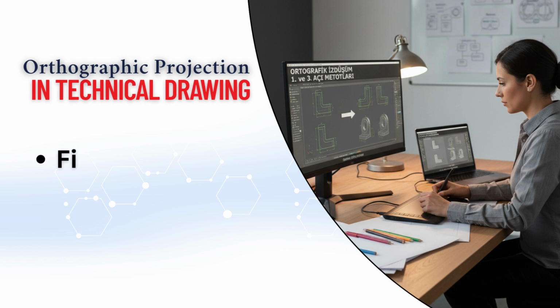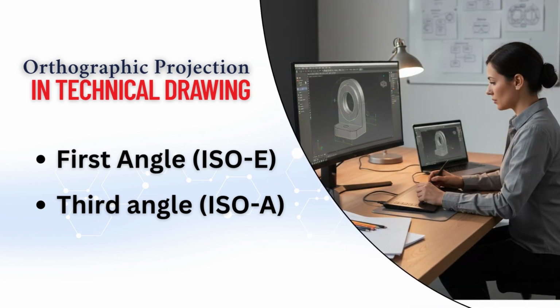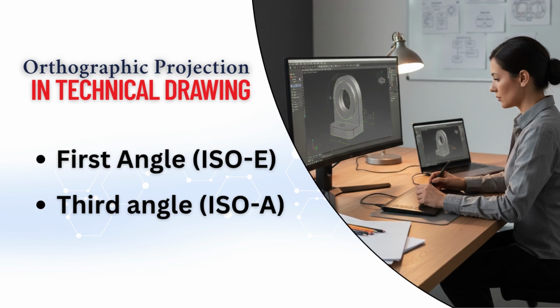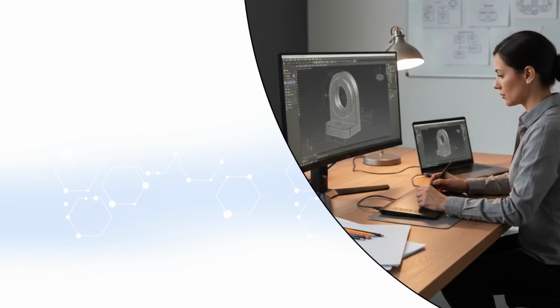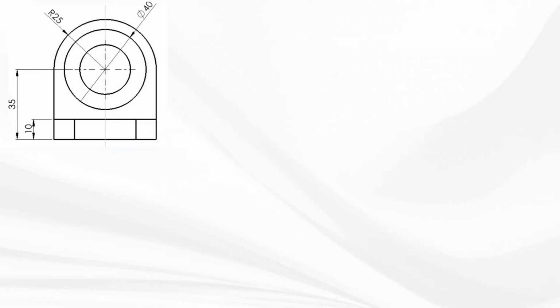The basics of orthographic projection. Technical drawing is one of the clearest technical communication tools used according to international standards. Orthographic projection is a method of representing a three-dimensional object by projecting its surfaces perpendicularly onto two-dimensional planes. The purpose of this method is to show the geometry, dimensions, and details of an object accurately, using the minimum number of necessary views for production or assembly.